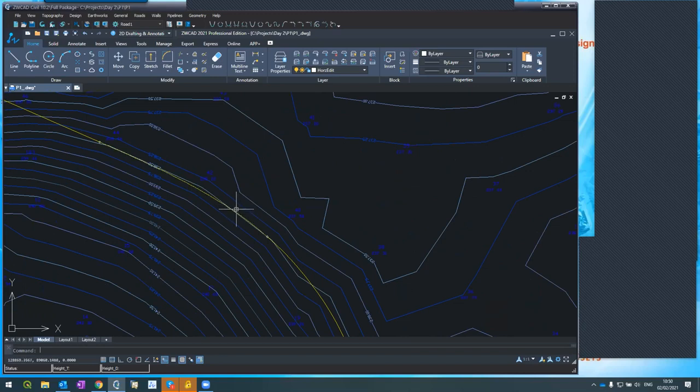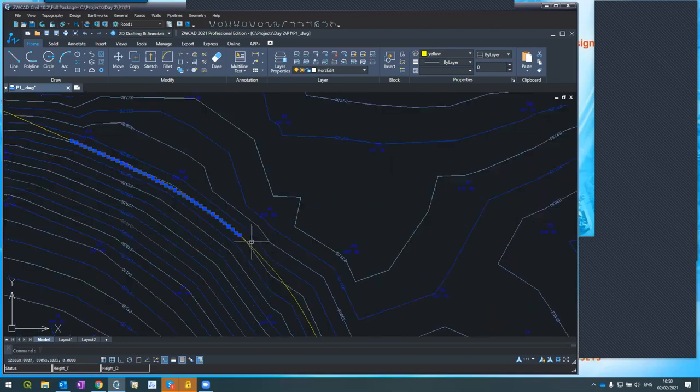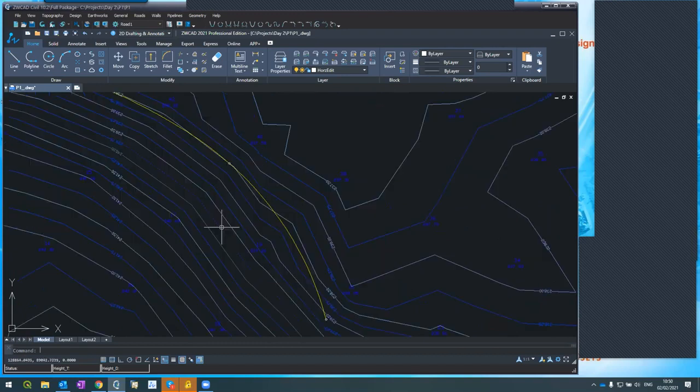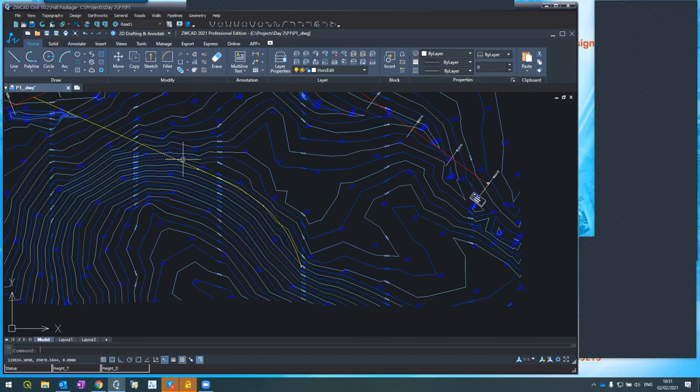In this case, the system created a transition curve, a clothoid. This is the clothoid which was created. By the way, it took the arc and shortened it a little bit so it would fit exactly to the clothoid. So actually, what I told the system is, connect the line with the arc and automatically calculate the transition between them. Because my geometry here is bound to this. This is the geometry that I want, going along these contour lines. I hope you follow it. You'll practice this in a minute. Let me finish.